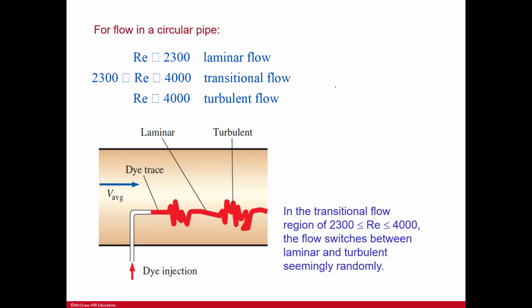Here is a range that you can see for a circular pipe. So you have 2300, less than or greater than, and this is Re for transitional, it's 4,000. And so you would have turbulent over here and laminar over here. Oh, it's down here.